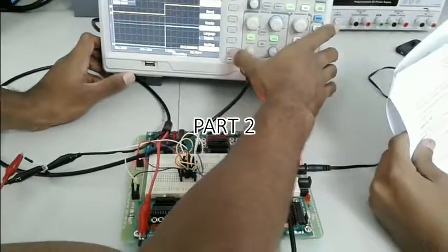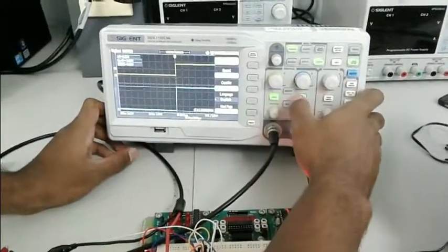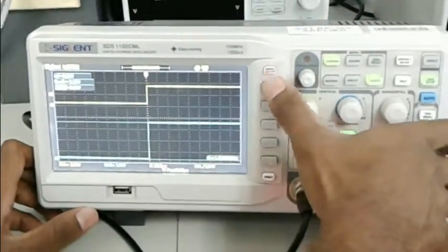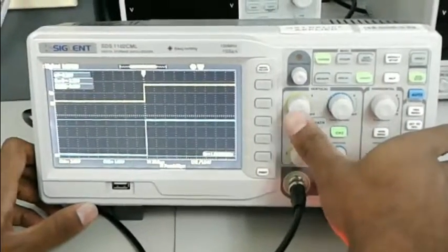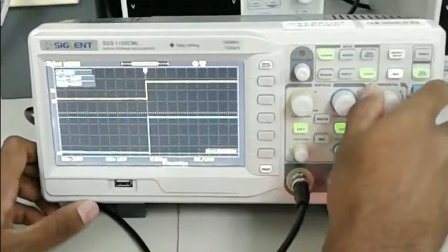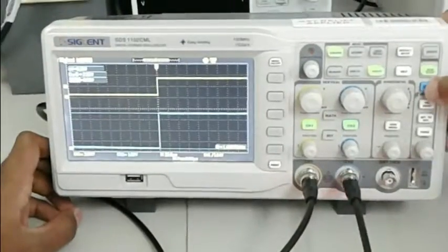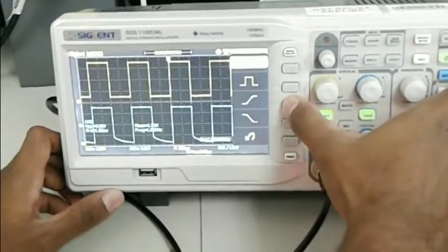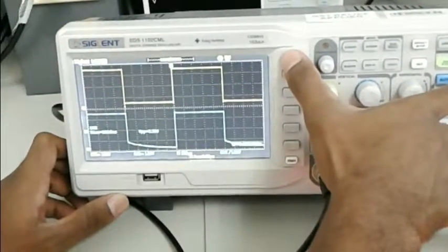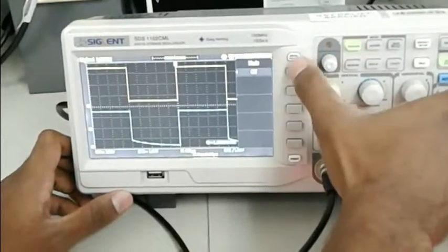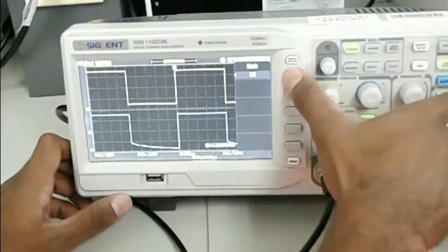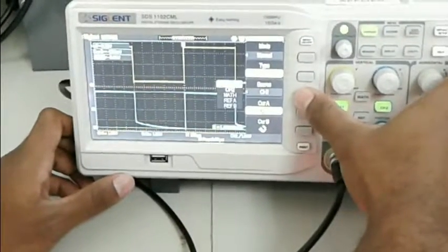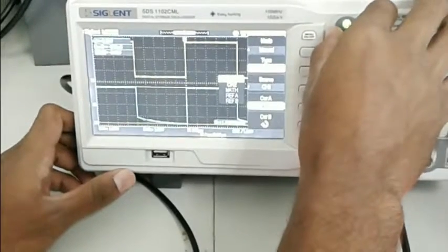Good afternoon. In this video, we'll be finding the total propagation delay and voltage levels for a wired 4 NAND gates as a series of inverters. First of all, we adjust the blue graph in order to find the voltage. We select the high edge graph, go to the cursor, and change the mode to manual. Then we adjust it to channel 2 in order to find the voltage.